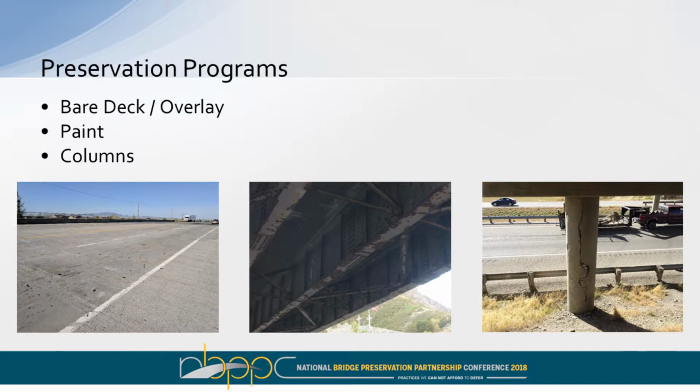So we've been looking at our preservation programs pretty significantly. We've got 3 main programs that we're looking at right now. We try to get an overlay on every one of our bridge decks. We're getting away from asphalt overlays, so it's either a thin bonded or a polyester concrete that we're using most of the time. So we've got our bare deck overlay program.